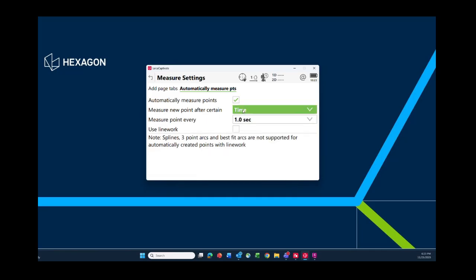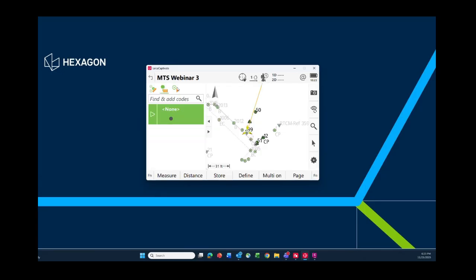If I pick distance and a foot and press OK, you get that additional page right there. And you get a different range of point ID. I'll go with the 10,000 range for those. And I'll measure those points on the wall here, just to demonstrate. And when you're ready, you can also do some offset. So you can enter an offset right and left. And when you measure your point at a specific distance, it also will add a point offset left or right.